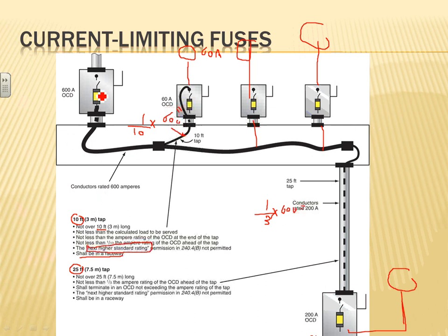The same thing here. If it's 60 amp, then my conductor here cannot be less than 60 amp. So you go to the table based on the lugs. Most of the time, these are 75-degree rated lugs because it's 3-phase. When we tap, a lot of these are 3-phase, so if you have a 3-phase load, 99.9% of the time you're talking about lugs rated for 75. So you go to the 75-degree column and size yourself a conductor that can carry 60 amps or more. I thought this is really interesting, tap rules. I do have a couple more tap rules, guys, that I will go over when we do the transformers, with primary and secondary protection and primary-only protection.